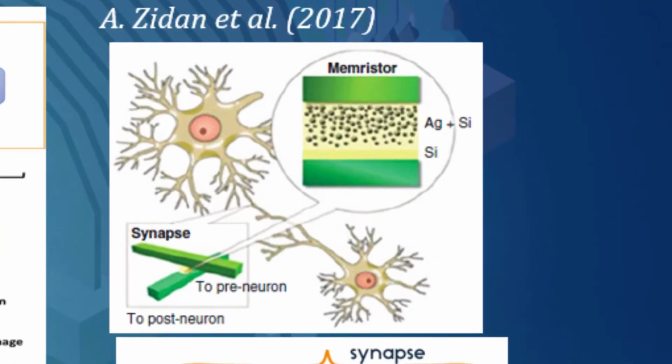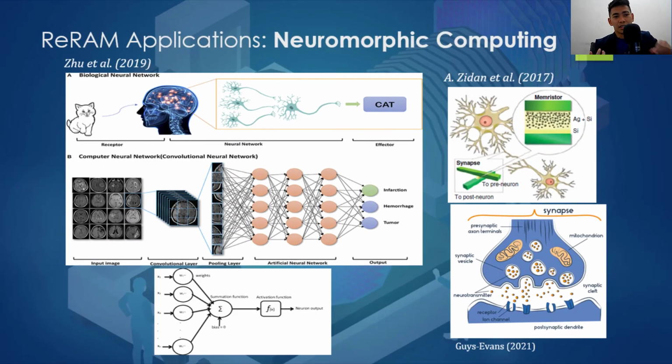So the figure on the upper right shows an example of a single memristor device acting as a synapse and reproducing the STDP behavior of a biological synapse. So like in a biological synapse, a memristor can store at the same physical location. Remember in the titanium dioxide example, when we force a positive step voltage, the oxygen atoms are ionized, and when the slope of the voltage is now negative, it produces some oxygen vacancies and turns out to have some resistance, which can be used as a memory.